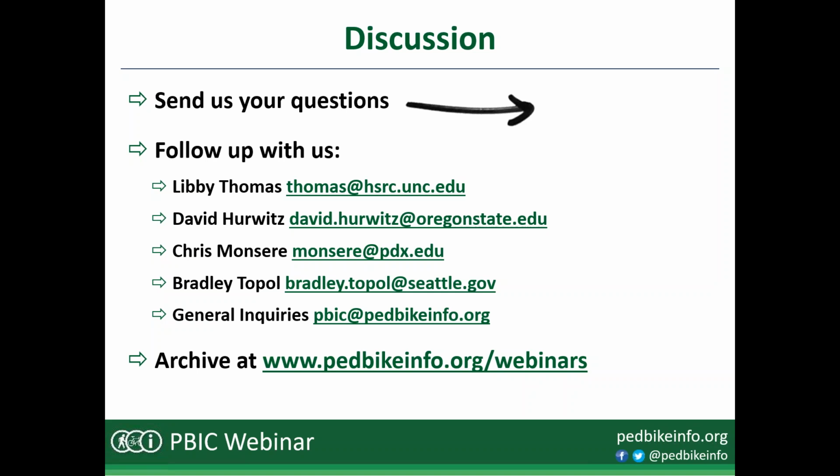And so we've used LPIs for those a lot, and that's why I said we're starting to do a lot more LPIs. I think the leading pedestrian interval is a really great starting point at any type of signalized intersection if you're just looking to increase pedestrian comfort as well as pedestrian safety. It has really low impacts to LOS. I mean, it's 3 seconds per phase, but it definitely has high benefits. That's why it's an FHWA proven safety countermeasure, a 60% reduction in